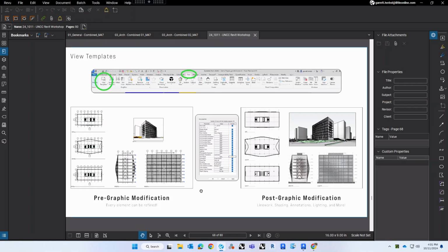What I will at least say is that the Revit components that come with things like levels, things like grids, section markers, and elevations, you do not have to keep those. You do not have to stay with those very ugly, not pretty visual symbols. You can change, you can create your own just by going into the families of each.